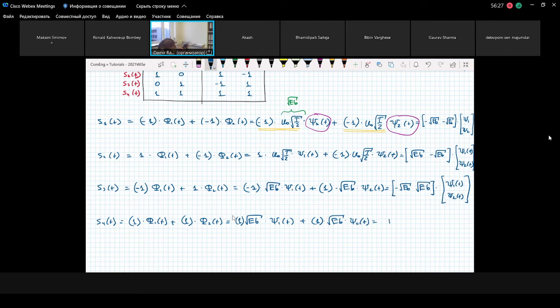And you see we have the elements of the first vector times phi1 of t, phi2 of t. So now we have everything ready for a signal space diagram. We just need to take the scalars inside the first vector and use them as coordinates of our points of the signal space diagram.